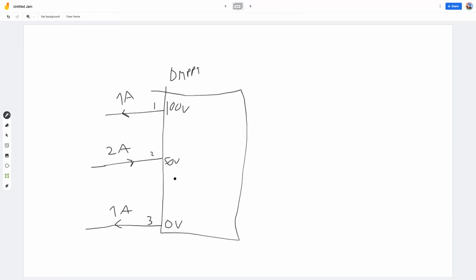So for example, what you can do is put an ideal transformer in between, right? Which does not exist, but if transformers would work for DC, you would get a transformer like this, where you combine this to that terminal, with 1 amp running through this coil. Of course, transformers don't work for DC, but if they did, you would have a converter with 50 volts 1 amp on this side, and an output of 1 amp 50 volts on this side.